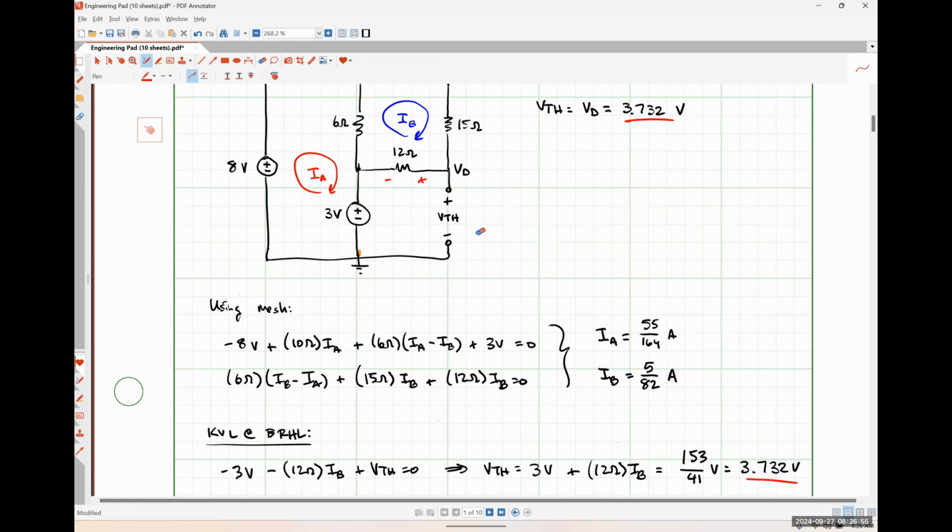Which resistor? The one we took out? So they're going to wind up being significantly different voltage drops. And I'll prove that here in just a couple of minutes, okay? It shouldn't be difficult to understand that they should have a different value of voltage, because our circuit analysis would be significantly different if that 20 ohm resistor were actually in the circuit, right? When we applied our mesh analysis, we would have had a third closed mesh and dealt with a mesh current that is not 0. When we applied our nodal analysis, our Kirchhoff's current law equation at node D would have had an extra term. So it would have resulted in a significantly different value for that voltage, okay?